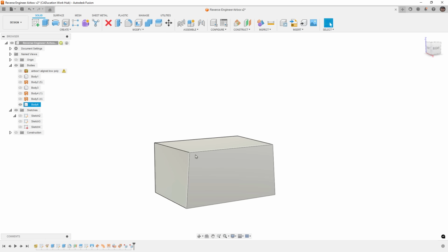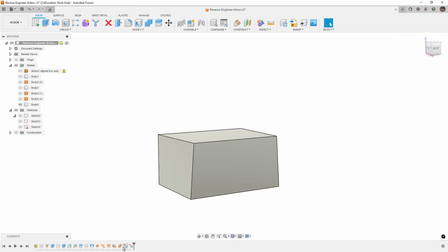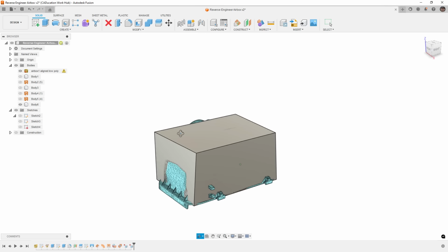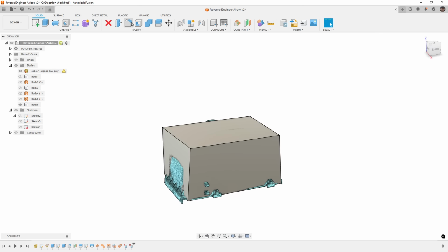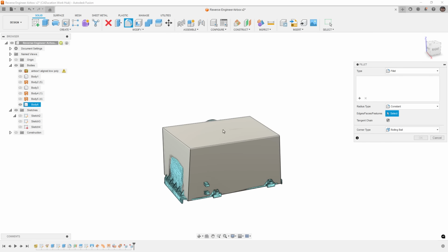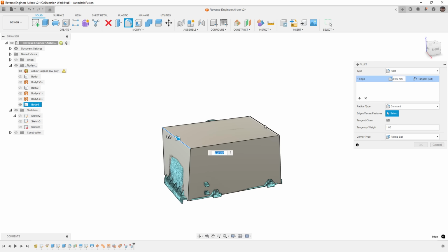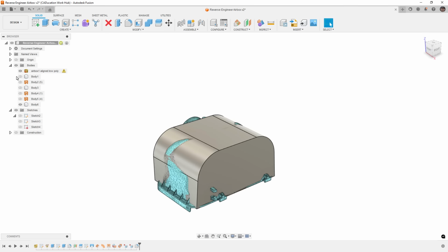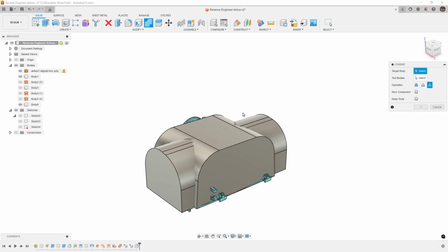The reason I don't want an edge there is because once we add the fillet to that corner, if those edges get really close, it just gets messy. So it's more features in the timeline, which generally I hate, but it is a little bit nicer and cleaner. All right, so we need to check what we've got going on here. So we're going to add a fillet. We may need to taper this top section, but I'm going to leave that in just a minute. I think we were at 60. Let's say okay. And then we're going to combine these two.